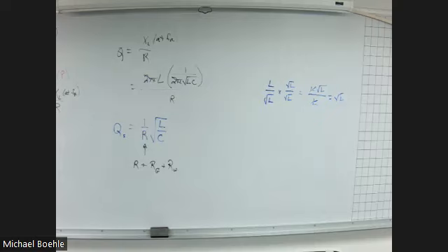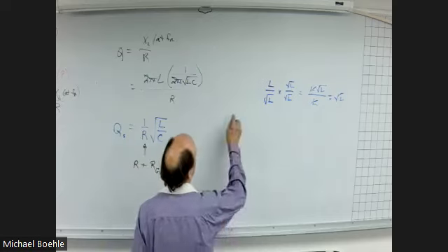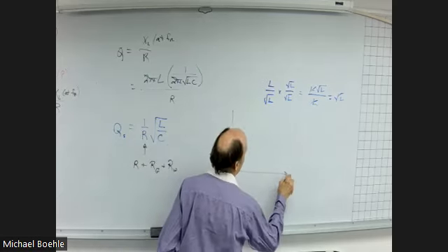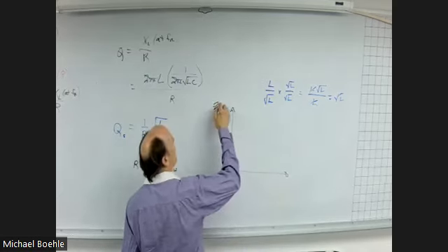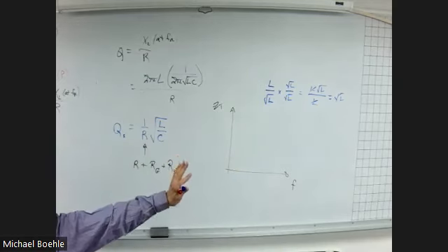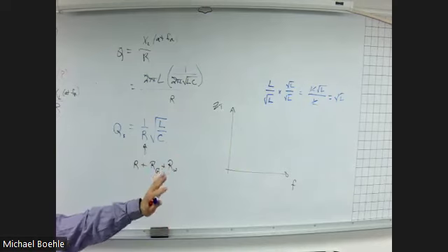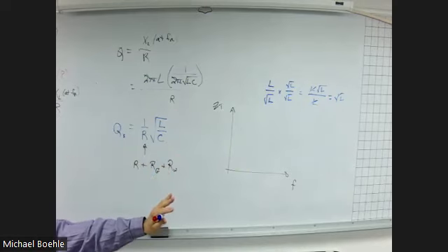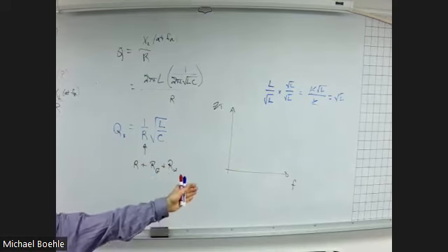Now he goes through a few other graphs here. This is kind of a fun thing to look at and think about. If we were to graph the total impedance of our circuit versus frequency, what's going to happen, right? At really low frequencies, the capacitive reactance is huge. It's going to dominate.